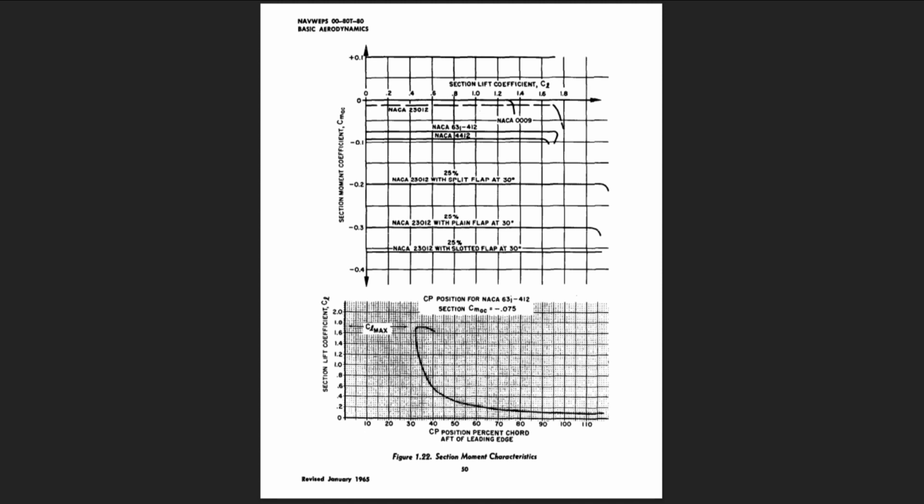The NACA 0009 airfoil is a symmetrical section of 9% maximum thickness. Since the mean line of this airfoil has no camber, the coefficient of moment about the aerodynamic center is 0, i.e., the CP is at the AC. The departure from 0 cm sub AC occurs only as the airfoil approaches maximum lift, and the stall produces a moment change in the negative, nose-down, direction.